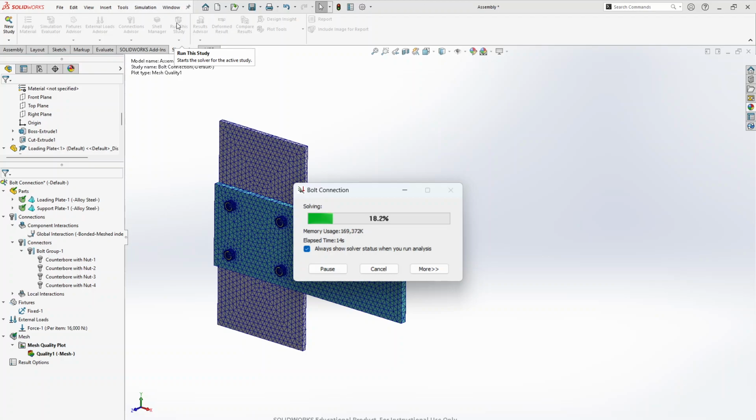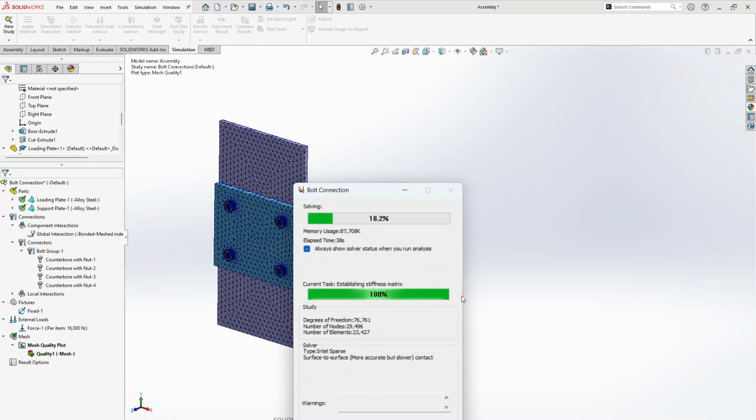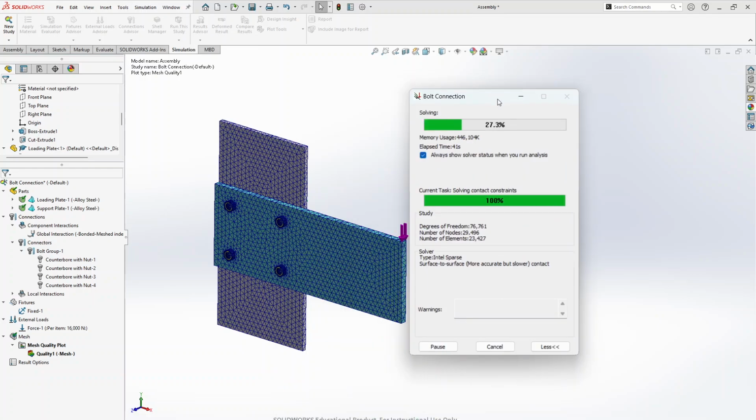It means, if the bolt is a correct selection for this assembly, are they going to survive, and are they going to meet that factor of safety of 2, which is like 200% safety, one additional 100% safety margin for the factor of safety for each bolt. Okay, this may take a while.